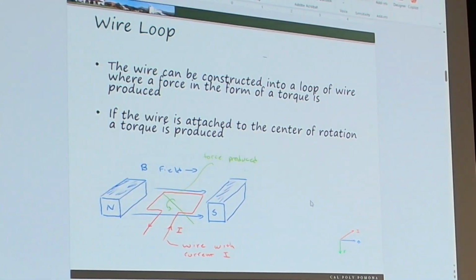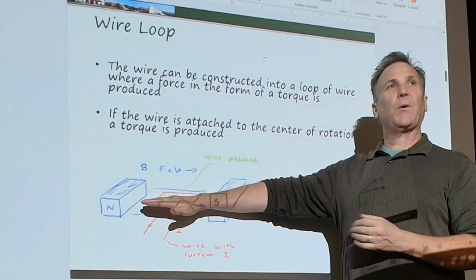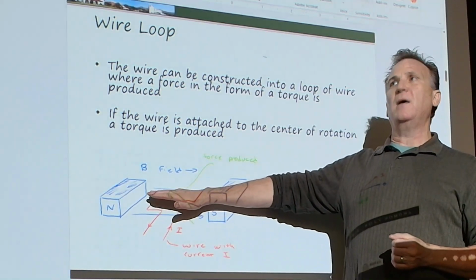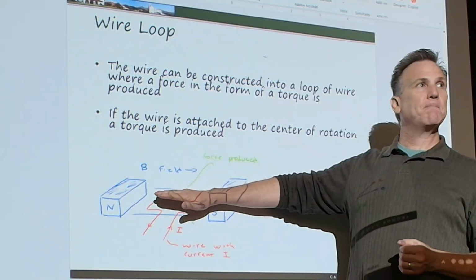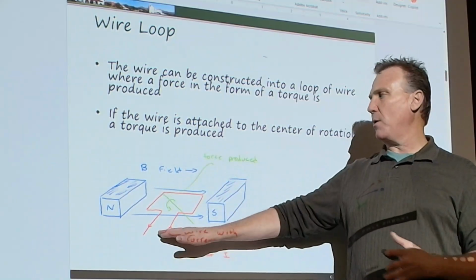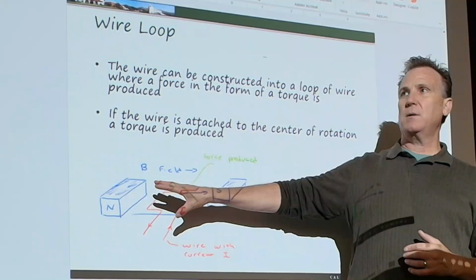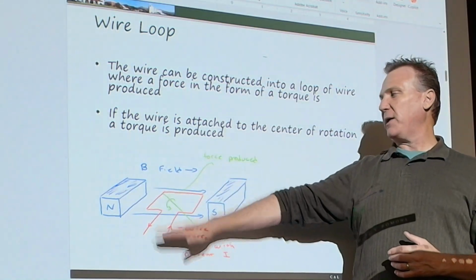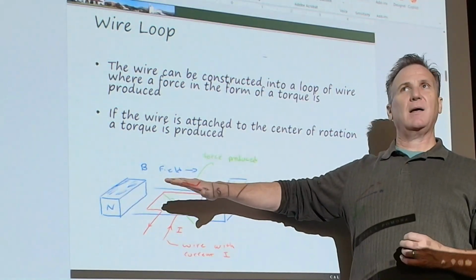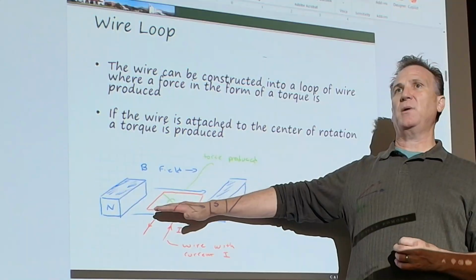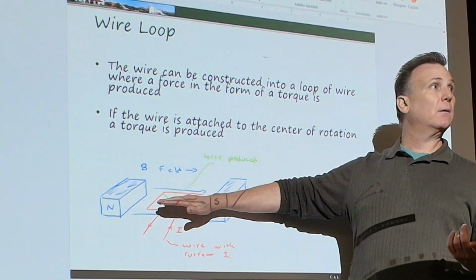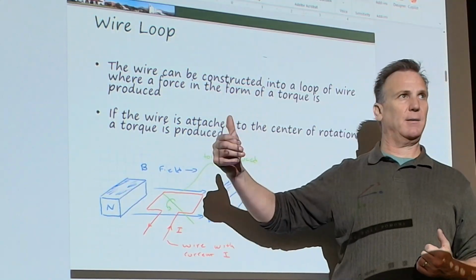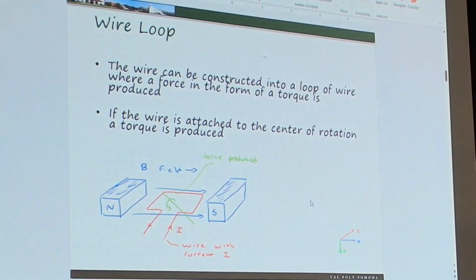So I squared R is the power dissipated as thermal power if it can't be dissipated in a mechanical capacity. Right? Power into my motor equals power out. And if I can't exhibit the electrical power as a kinetic power, then it's going to be reduced to a thermal power. Everybody see that? Everybody agree with that? So if that's true, the thermal power has to be dissipated.